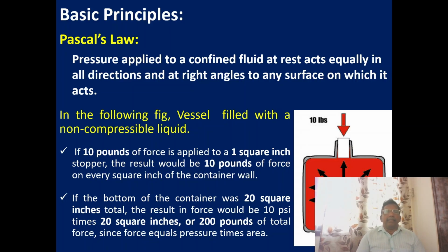Pascal's law: pressure applied to a confined fluid at rest acts equally in all directions and at right angles to any surface on which it acts. For example, you can see here a closed vessel with 20 square inch area, full of oil, a container full of fluid or any liquid. It's not a compressible liquid, it's a non-compressible liquid.